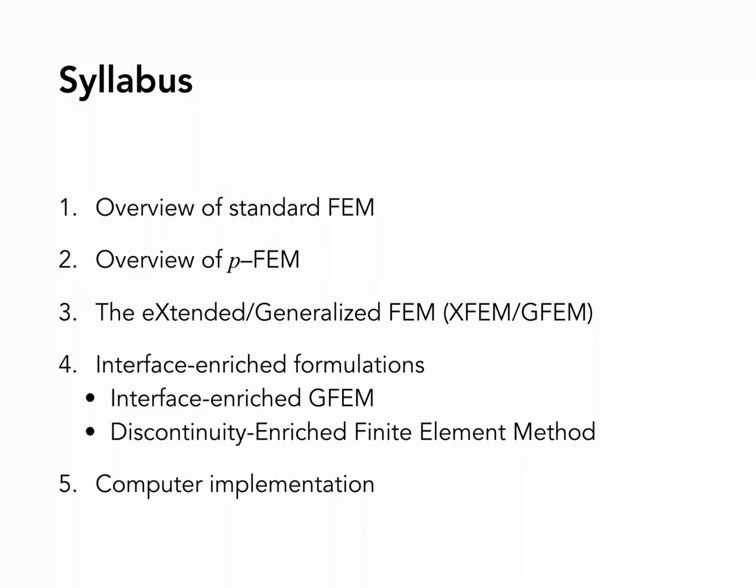And so there is really no difference in the formulation. The difference is that in XFEM, it was the first time that a Heaviside function was introduced to handle the discontinuity for the crack, so that the jump in the displacement happens within the element. So they introduced this Heaviside enrichment, and then they started calling it XFEM. But the method is the same. We will study these methods, and then we will discuss some of my work.